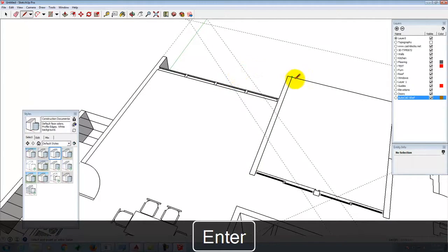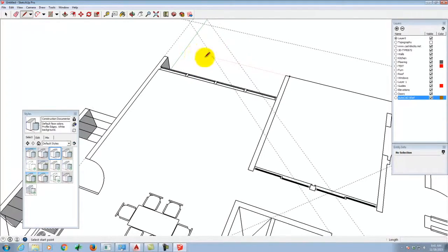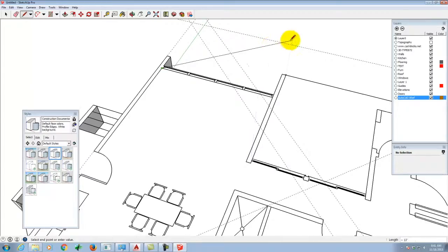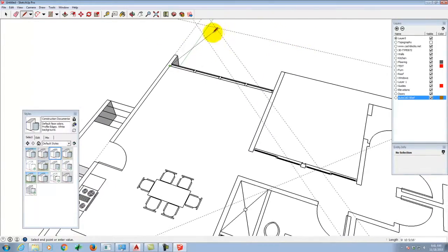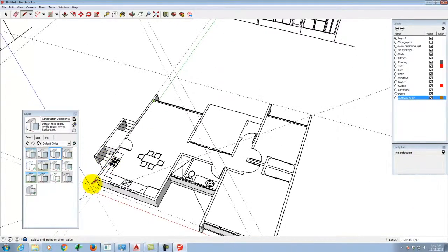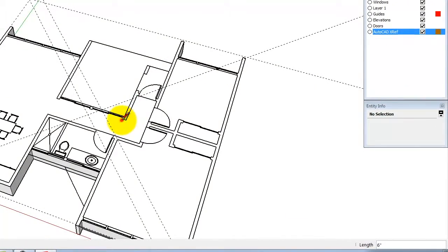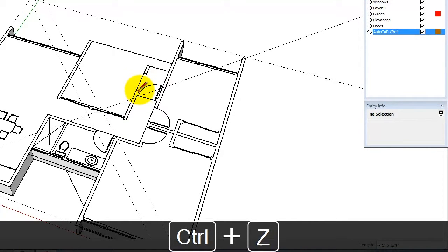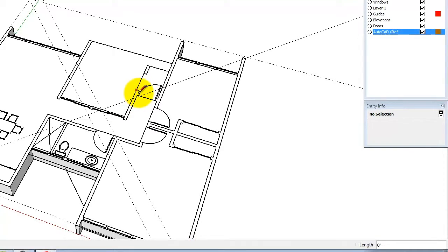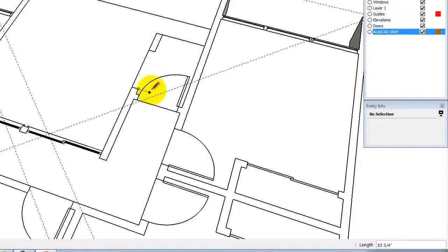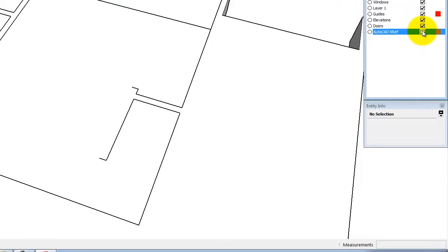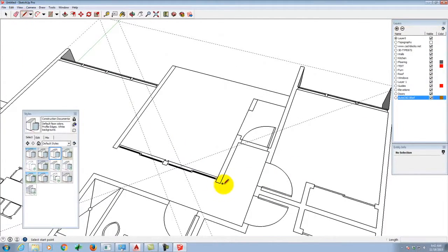So I'll stop there. And then we'll continue. It's having issues zooming. There we go. Notice that I'm going right over all of the doors. Right? I'm not trying to capture any actual openings. And I can double check my work by turning on and turning off my layers. Looks like I missed one segment of line that would go right here.